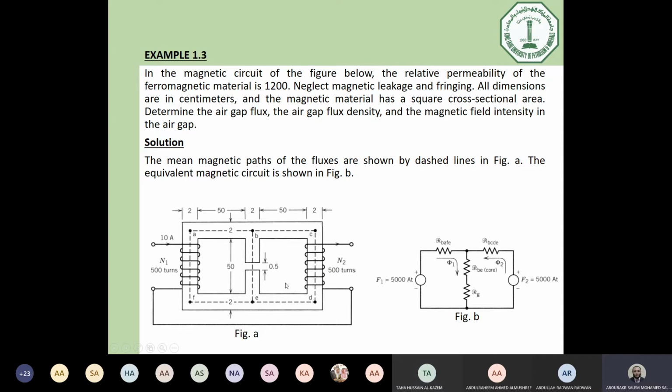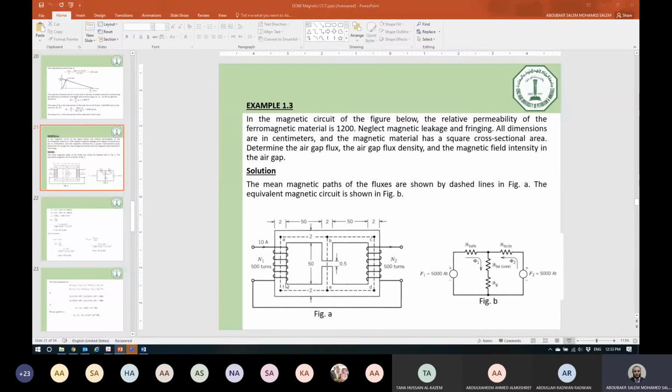So it takes the problem in steps. First, you have to recognize the dimensions. Secondly, convert the magnetic circuit to electric circuit. Third, solve the electric circuit using circuit analysis. After that, you can get any missed data. Okay? Of course guys, we have many configurations for magnetic circuit.